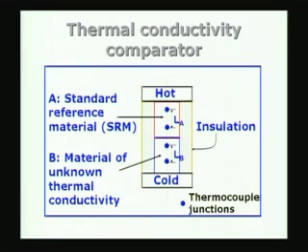thermal conductivity comparator, and it is very useful when you have the sample available in the form of rods, cylindrical specimens, and if you have a standard reference material, SRM, which stands for standard reference material, whose thermal conductivity has been documented extensively and is available in the literature, then we can take that standard reference material as one of the materials and prepare, as shown in this particular figure,